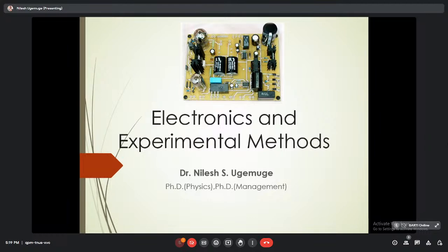Even after converting AC to DC with the help of a diode, we are not getting pure DC. If we want pure DC, then we use a circuit called an RC circuit or a filter circuit, an L section or pi section filter. After that, we use components like the Zener diode to create a regulated power supply, which we call a ZRPS, a Zener regulated power supply.